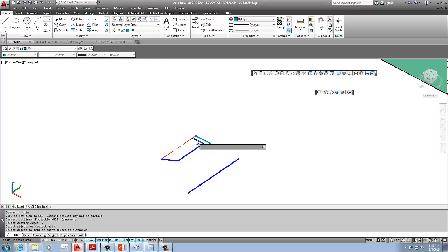So when you create these geometries, you have to have what's called a valid revolvable geometry. No figure eights, no crisscrossing, no loops. And so this is a profile shape that can be revolved. And I'll create a region out of that.